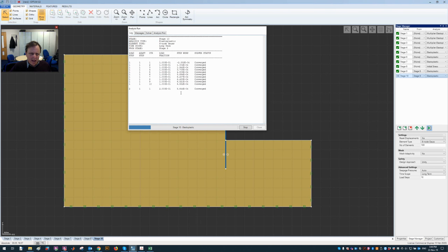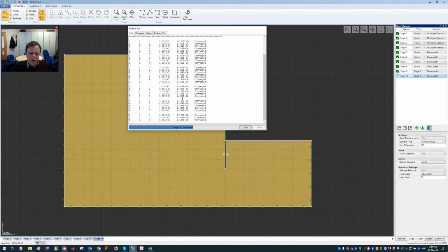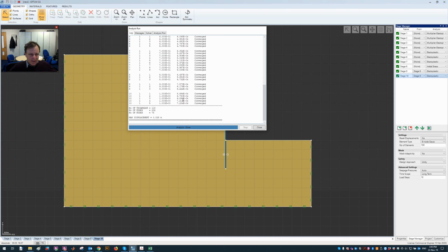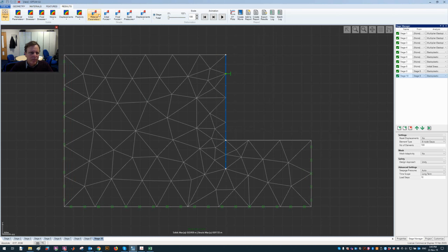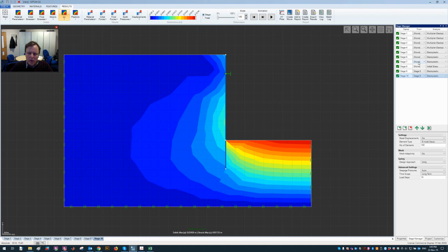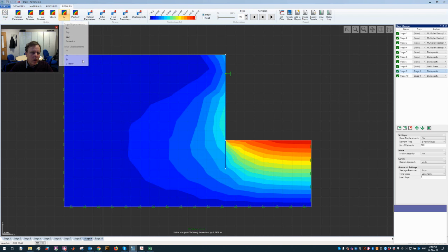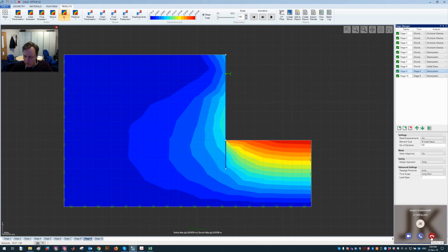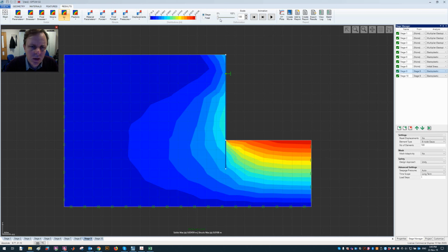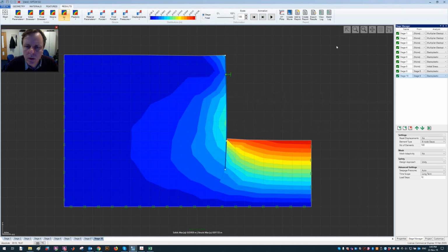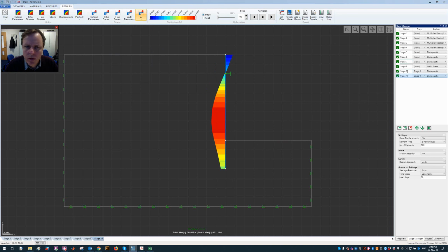You can have some weird effects, with convergence difficulties to start with. It's because this is a nonlinear problem, and just shrinking these residual forces is not necessarily a great thing to do. Let's look at the displacements. That's how it looks for 10 steps, and that's how it looks for a single step. Let me blow that up by the same. So for the 10 steps, there's a difference. It's quite a significant difference.